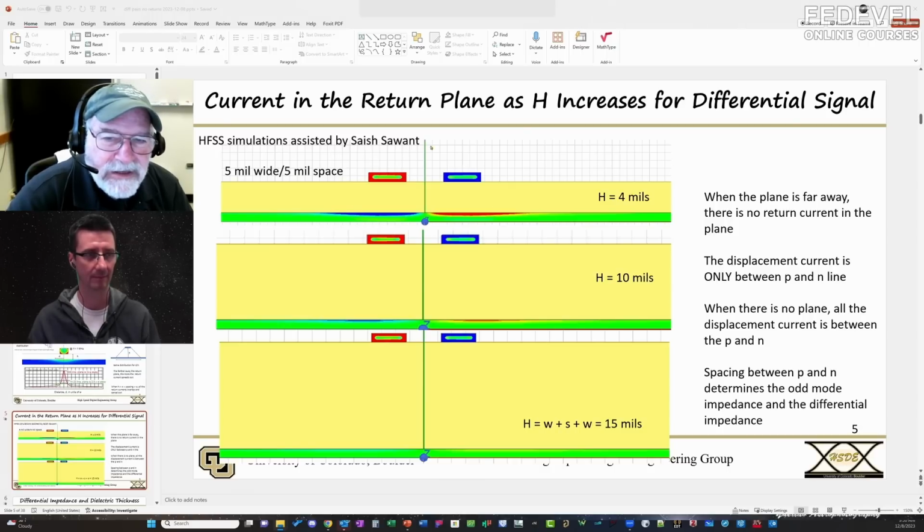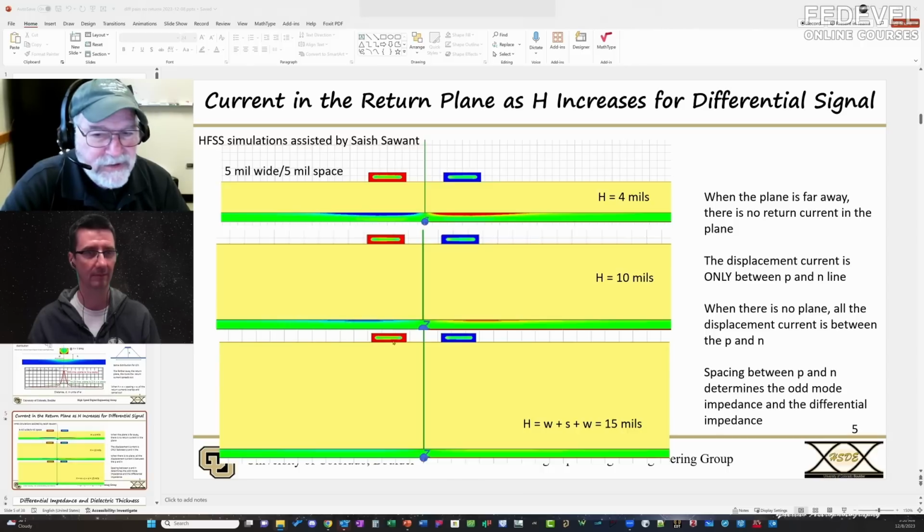This is the environment where we have traces on circuit boards. This is the environment where we have unshielded twisted pair. They're still differential pairs. They're still two single-ended transmission lines with crosstalk. It's just two different behaviors, two different regimes because of that distance to the return current and how far away they are.